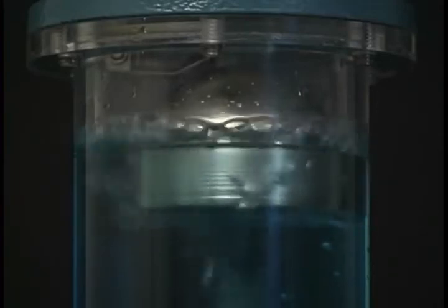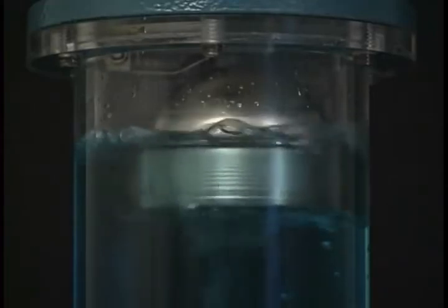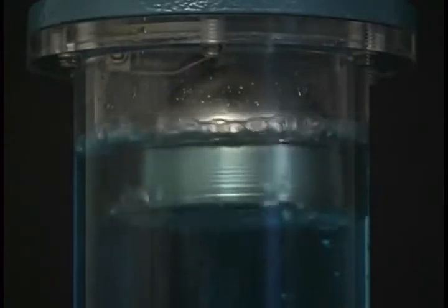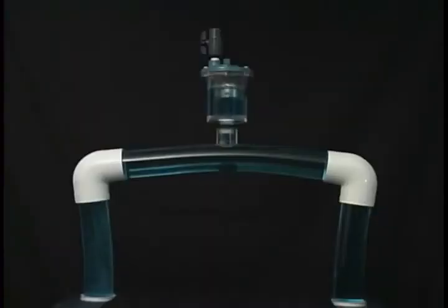You can see how the Type 316 stainless steel float fluctuates to allow air to be vented while the water is contained. An air release valve will continue to open, releasing air during system operation, because forces acting to open the valve are greater than forces acting to hold the valve closed.